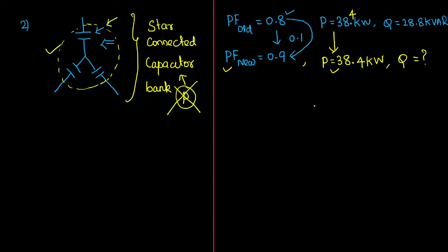So now I'm asking you, just by using this new power and new power factor, can you calculate the reactive power? Is it possible? Yes, it is possible. How, sir? Let me prove it to you. Listen, what is the formula to calculate the apparent power? It can be calculated with the help of V into I conjugate. Of course, I agree with that.